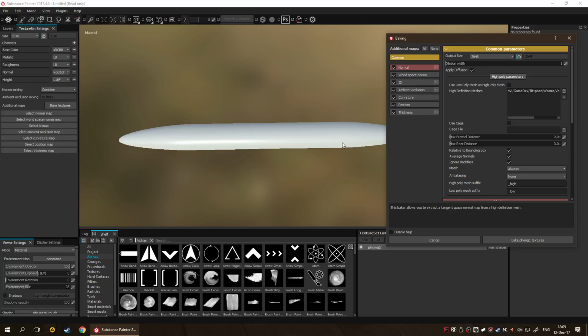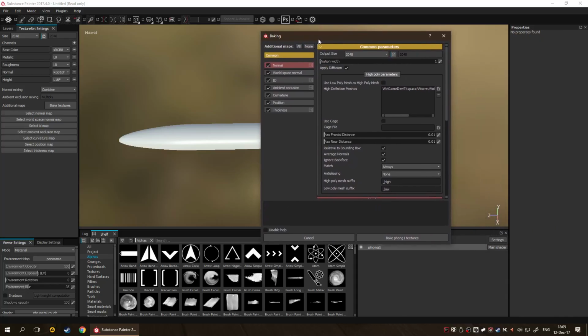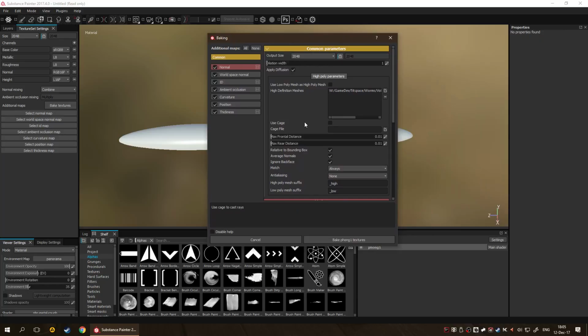Whenever you have two pieces of geometry, such as in this case, we've got our high definition and low definition mesh, whenever the ray goes through the high definition and the low definition, that's basically a point of contact, and it allows for the high def to be essentially projected on top of the low def using the UV coordinates, which you have presumably done fairly well in order to avoid some of the issues that we mentioned in the previous video about PBR.